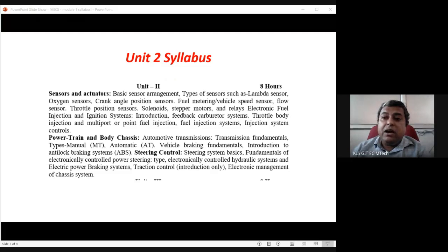So just imagine how fast the resistance changes from mega ohm to simple 5 or 10 ohm. The rate of change is very fast. When light is there, resistance is very less, 10 ohm, 100 ohm or something. When it is dark, resistance goes into mega ohm. So that is actually a light sensor, called an LDR. So you understand what a sensor is.